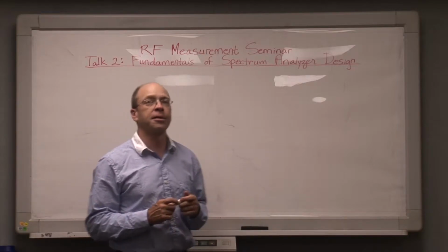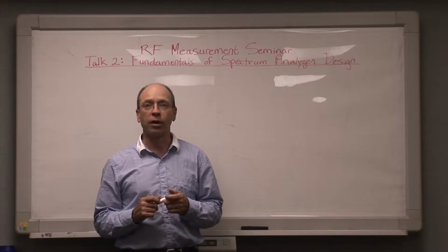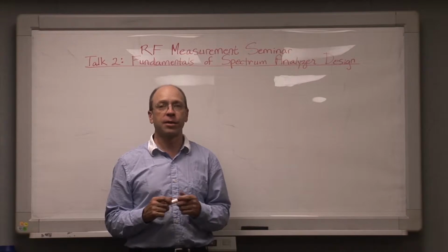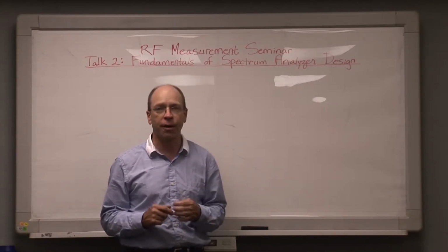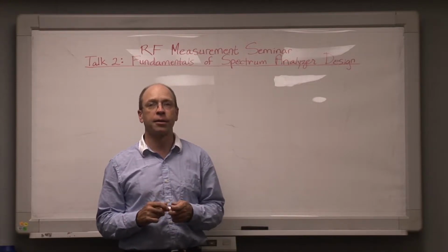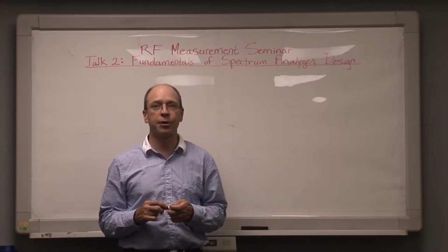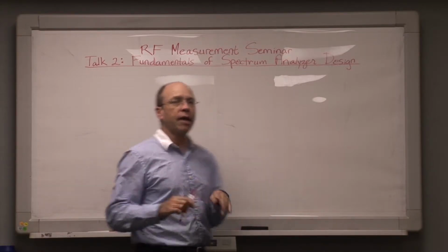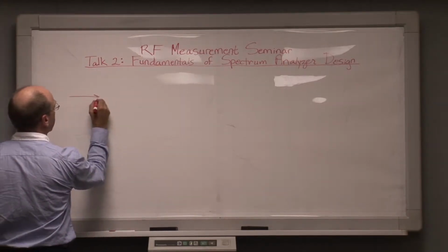A spectrum analyzer, as the name implies, is designed to show us power in a spectrum as a function of frequency. As we'll also see, it's possible to run a spectrum analyzer in a 0 Hz span mode in which we actually see power as a function of time. But the important thing to remember is that the spectrum analyzer normally shows the actual power in a measurement circuit, not the voltage.